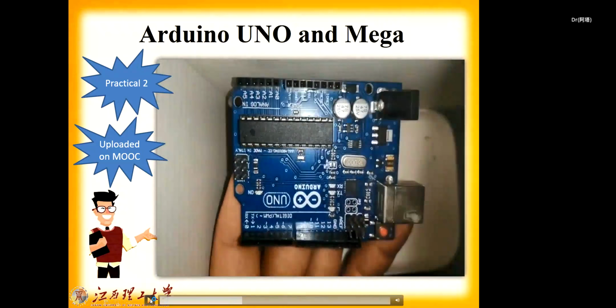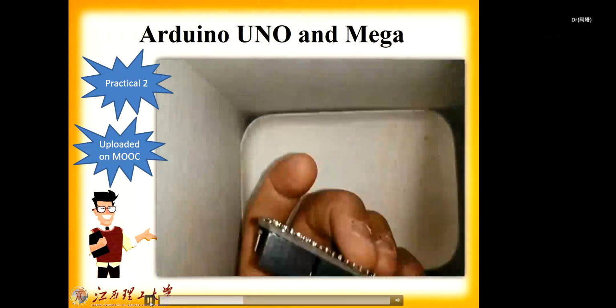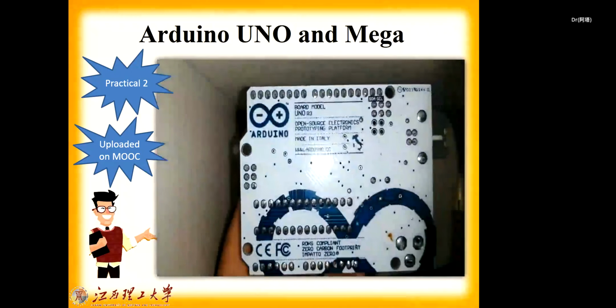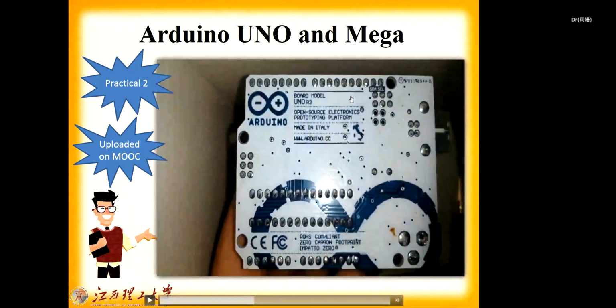These are voltage pins with different voltages like 5 volts and 3.3 volts and some ground, which is very useful to run some limited modules for your project. But you should be careful not to draw too much current from them when you are using them. From the back side you can also see the pins going out. That is why we advise never to use Arduino boards on metal sheets or any conductive place.